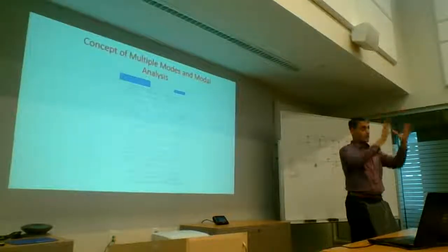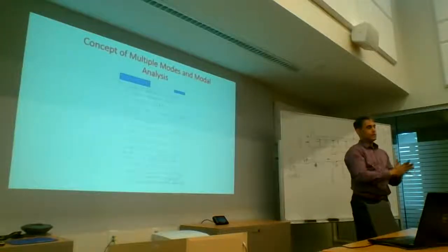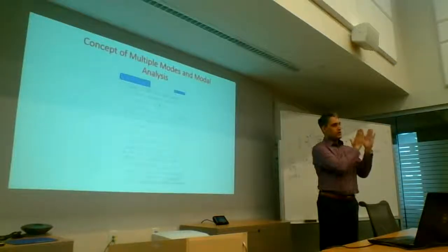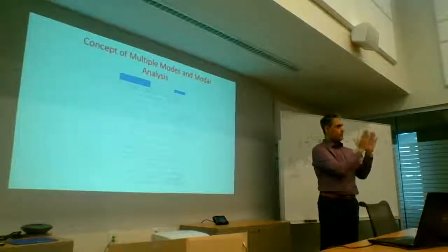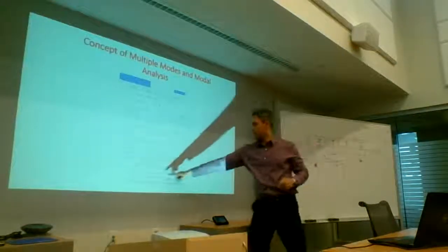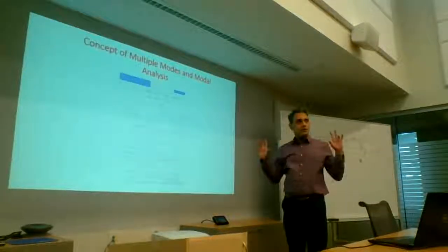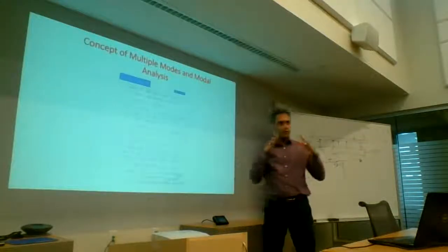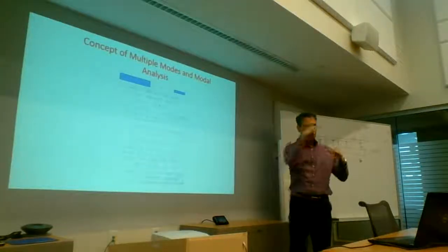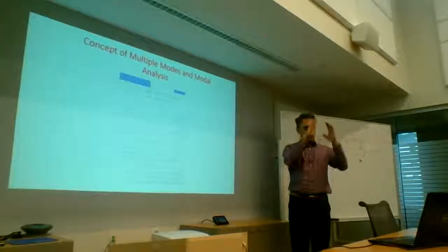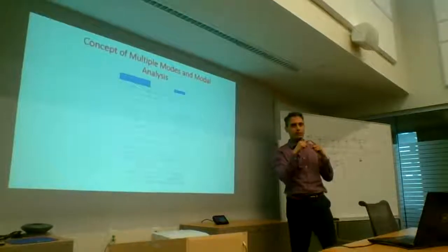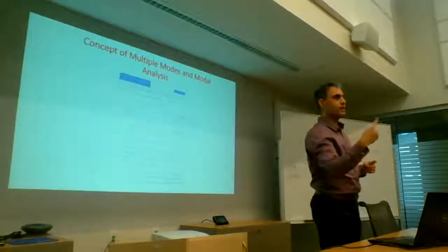So now your overall multi-degree of freedom system has been decomposed into independent sets of single degree of freedom systems with different periods. So now this equation is applicable to a particular mode. And this is again a matrix equation, so M is a diagonal matrix. Because that's been diagonalized, it's one equation, one equation, one equation. They're not simultaneous. You don't have to solve them together. They're all independent. So each equation can be solved independently.